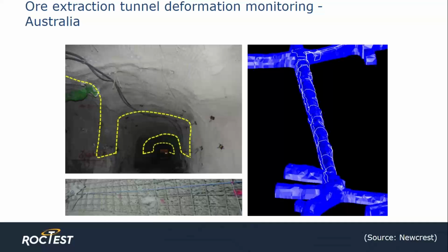The Hydro&Geo sensing cable was installed with the goal of providing a good bond between the cable itself and the tunnel structure, thereby ensuring good strain transfer and high sensitivity from the tunnel surface to the sensor. The cable was affixed to the walls with plastic and metallic clips and onto the mesh behind the tunnel lining using cable ties to facilitate proper orientation behind the lining.